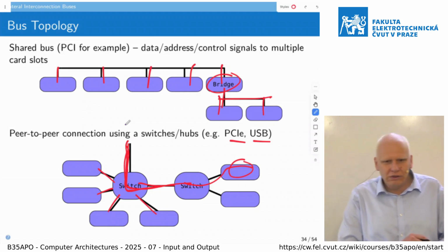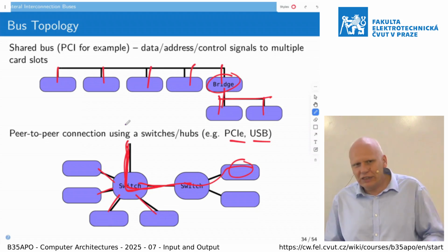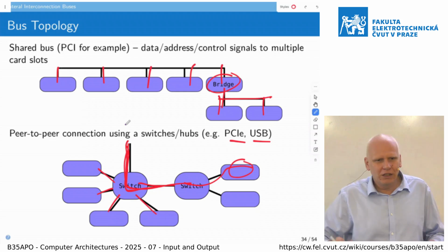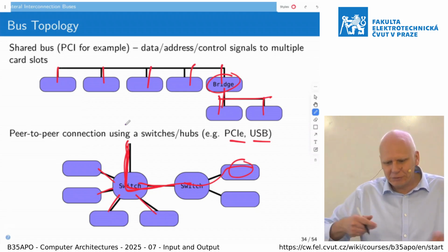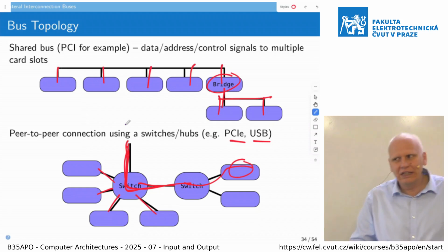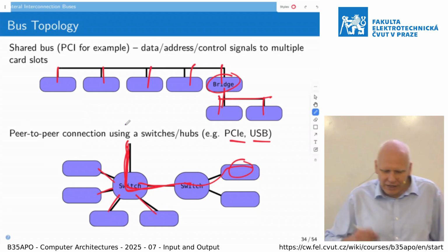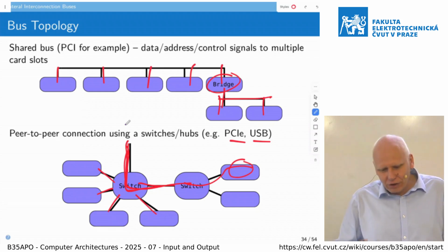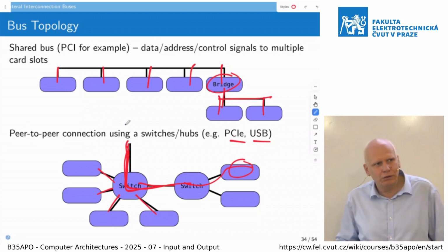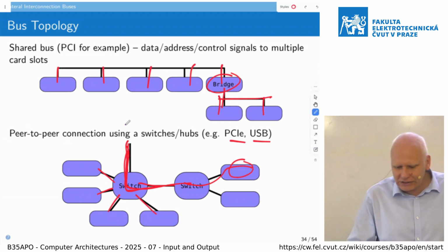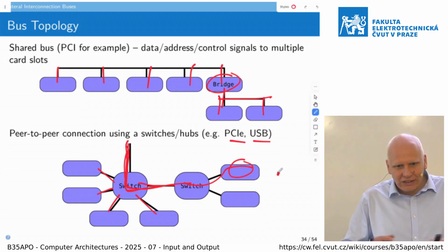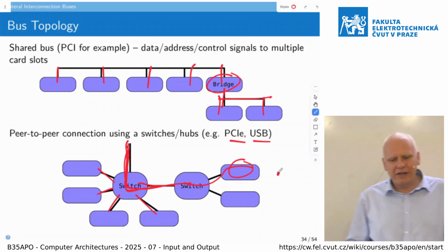If you need to deliver the data to USB or video, for example, through the USB and PCI Express to the hard disk through the PCI Express mapped SATA controller and then to the disk and so on, it is great. But if you want to have a fast control with low latency, it is quite interesting how problematic it is even on those modern devices, and it is much easier even on small MCUs, which are much more tightly coupled to the peripherals and so on.